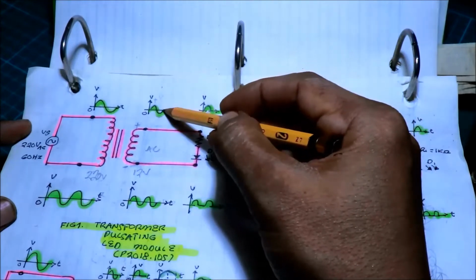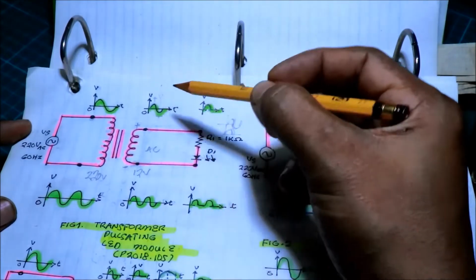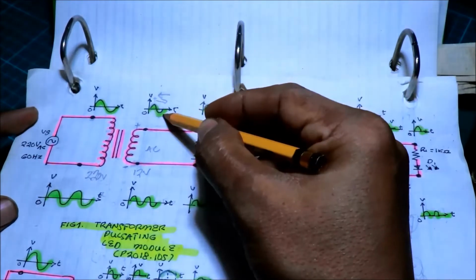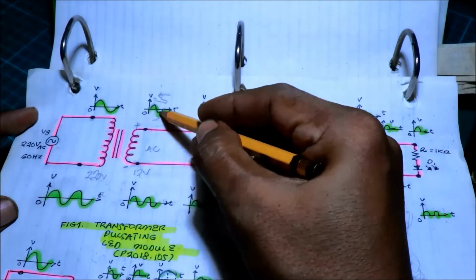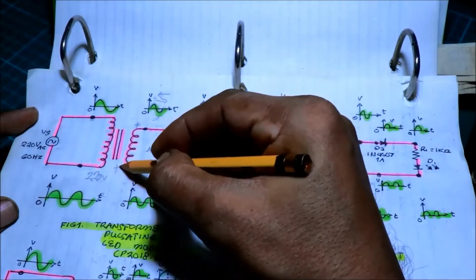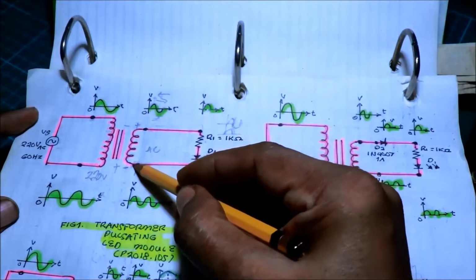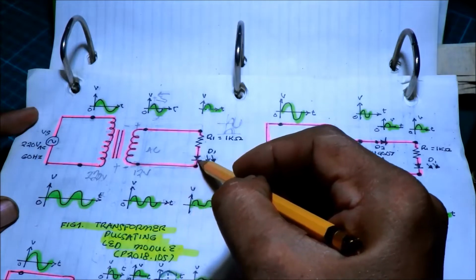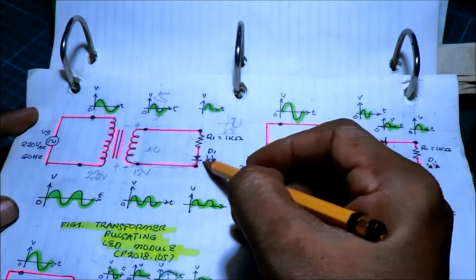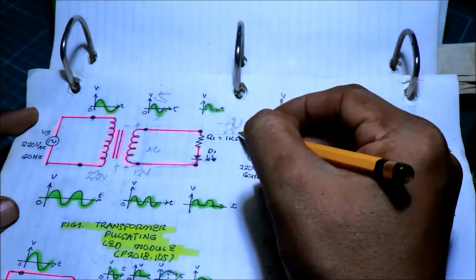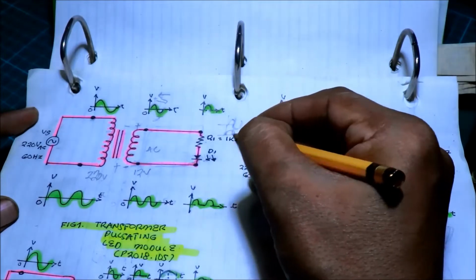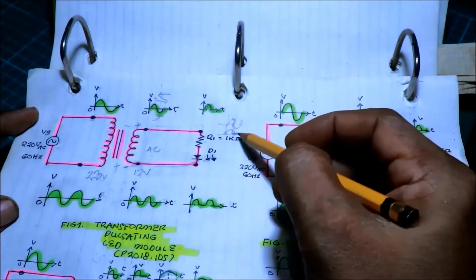During the negative half cycle, or the reversal of the wave, because the wave is traveling forward and then reverse, the polarity of the transformer will now become positive here and negative here. So the current now flows in the opposite direction. Since this is a diode, the LED, there's no output. It is reverse biased. So the output is this, flat. From positive to negative half cycle, flat. That makes the LED blink.